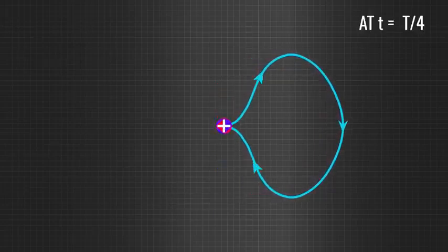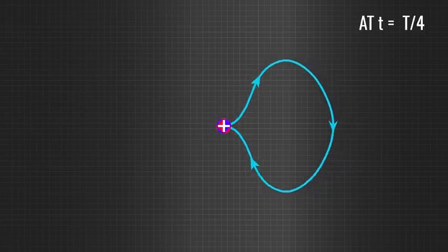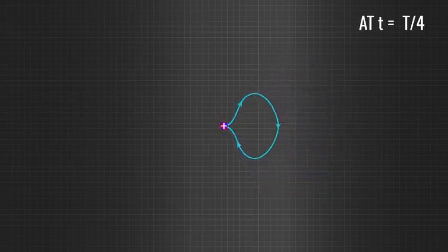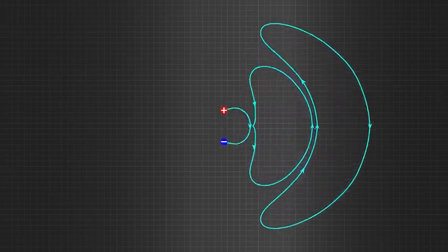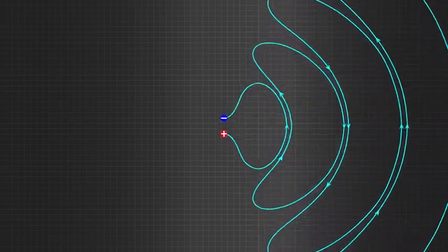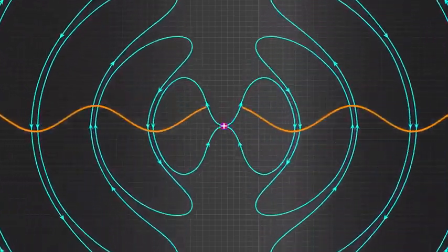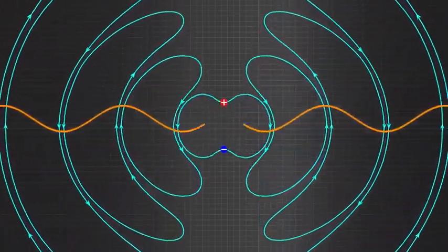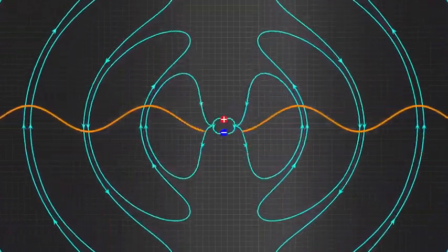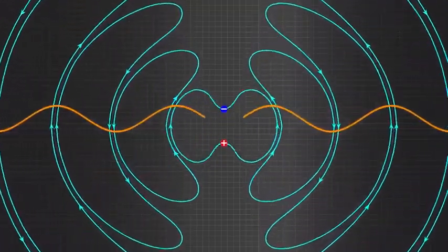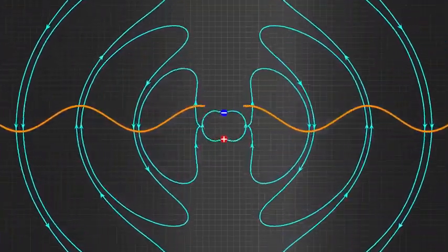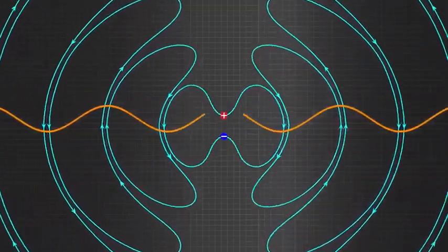When 2 charges meet at the central point, the deformed line also meets there. After that, it detaches and radiates. This radiation travels at the speed of light. If you plot an electric field intensity variation with respect to length, you can see that the radiation we have produced is perfectly sinusoidal in nature. Please note that this varying electric field will automatically generate a varying magnetic field perpendicular to it.